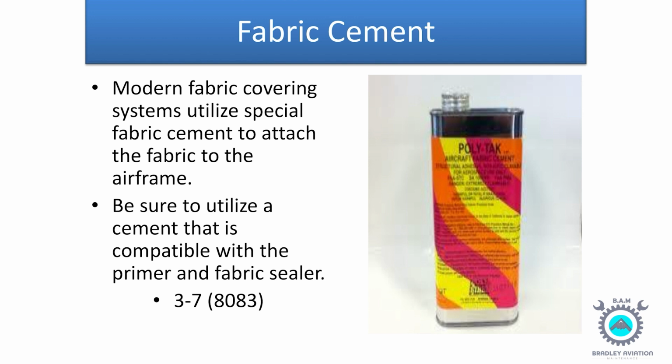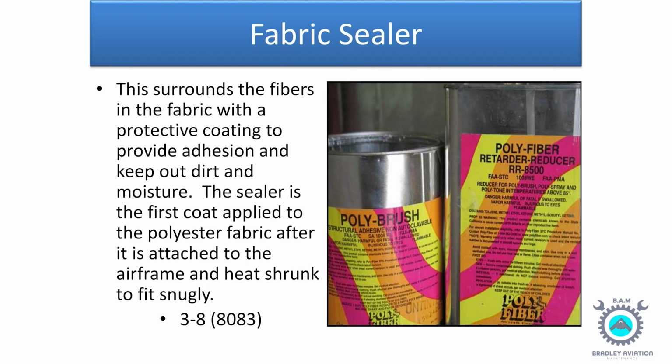3.7.8083. Fabric sealer. This surrounds the fibers in the fabric with a protective coating to provide adhesion and keep out dirt and moisture. The sealer is the first coat applied to the polyester fabric after it is attached to the airframe and heat shrunk to fit snugly.